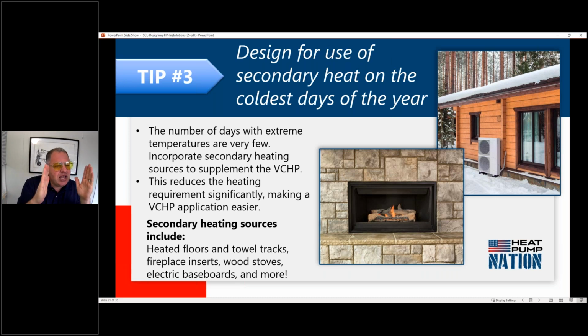And for those few days or maybe 50 hours a year that we are in what we call our colder extreme period, we design the home to use these secondary heating sources. The benefit of this is we need a smaller and possibly more efficient heat pump, which saves the homeowner money and energy. So these secondary heat sources are a wonderful way to convert a house, get the job done, and the really good heating contractors are doing this all the time.